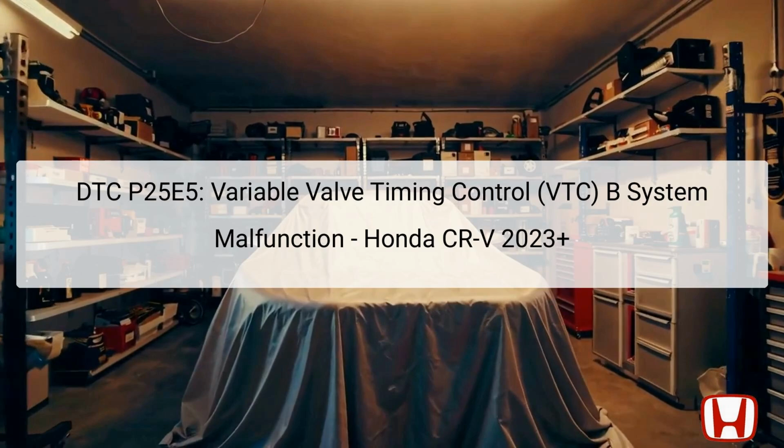This presentation covers the Diagnostic Trouble Code, or DTC P25E5, which indicates a malfunction in the Variable Valve Timing Control, or VTC, B system. This issue arises when the phase difference between the phase control command generated by the Powertrain Control Module, or PCM, and the actual phase of the exhaust camshaft falls out of a specified range.